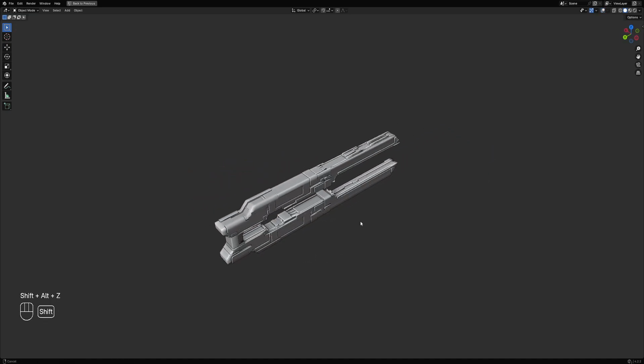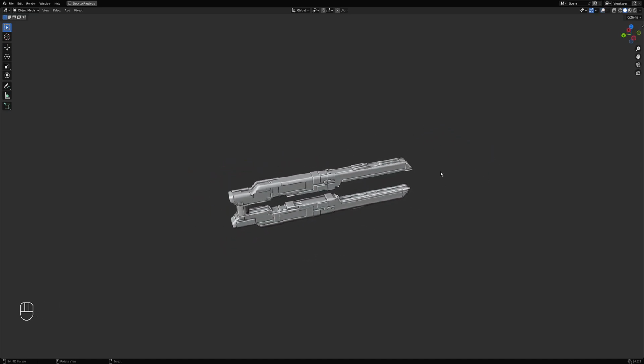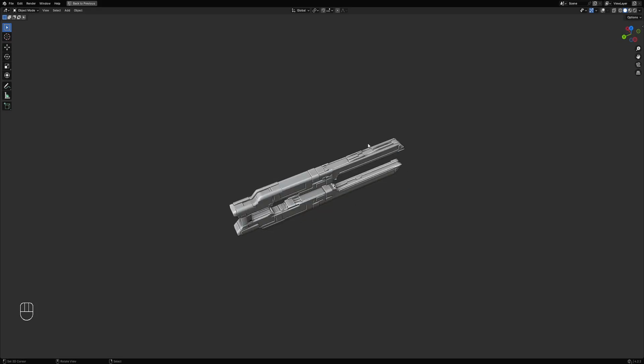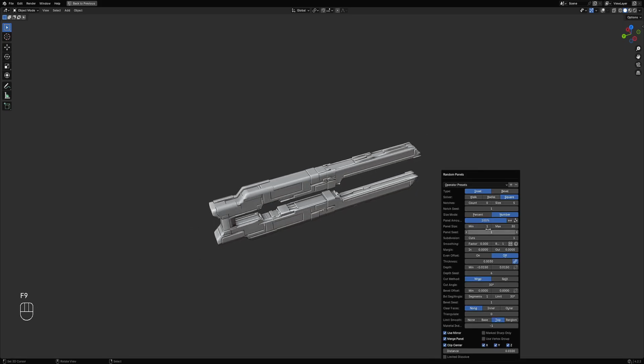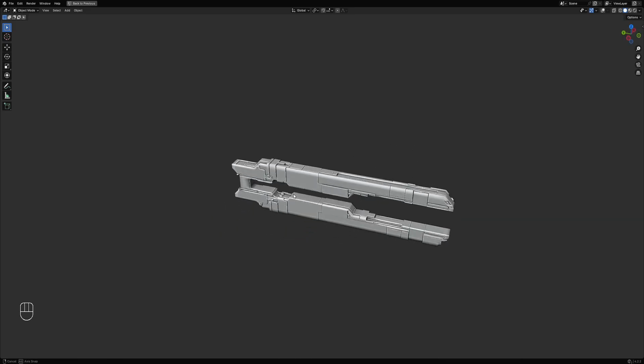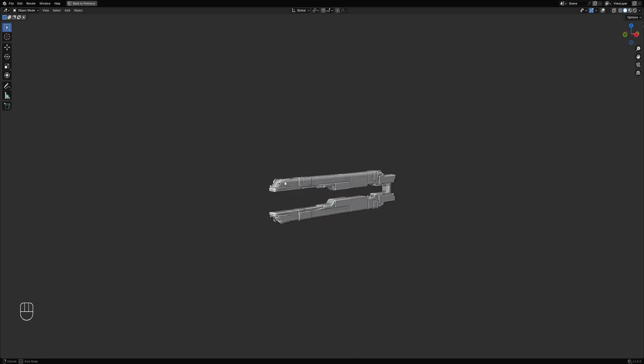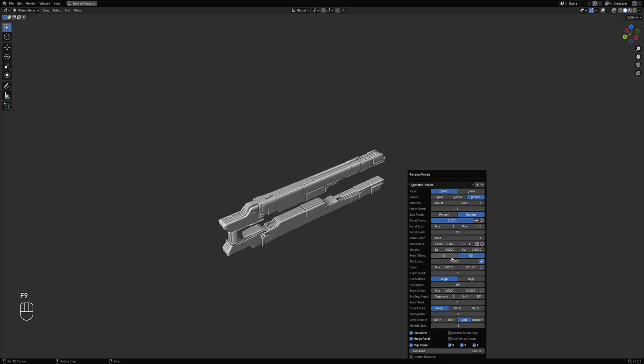So if you're just sketching for a background asset, you can quickly draw a sketch using the draw function and create a flow, then solidify it, then quadify it using quad faces, quad slice, and drop some procedural shader on it, and then you're good to go for adding it to your concept art piece, where you can of course draw over it or composite it to increase its believability.